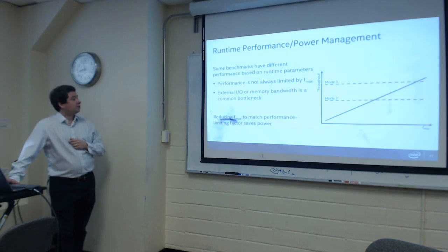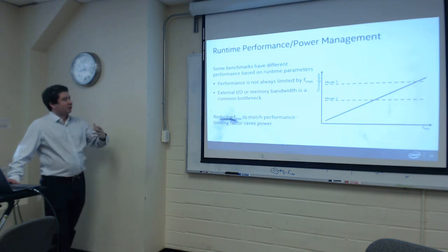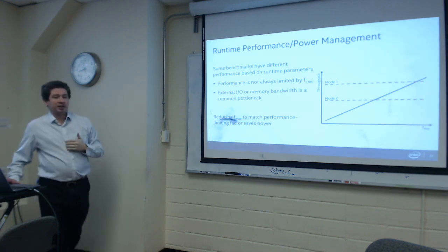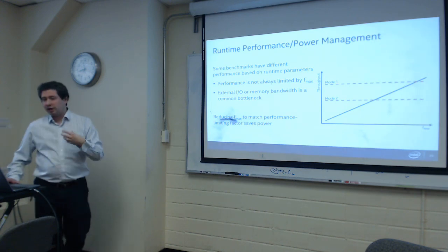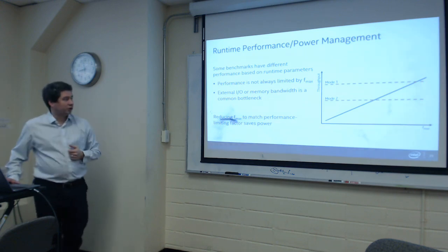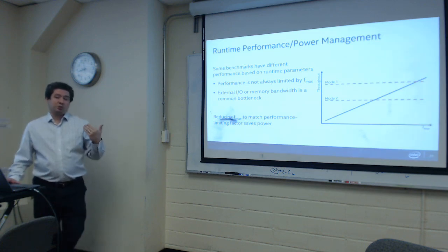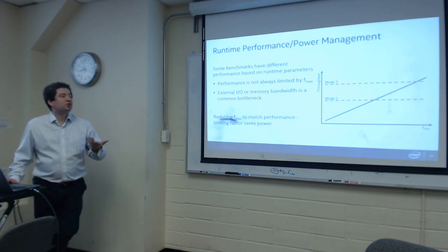Now, the last part I wanted to talk about is this idea of runtime management. Devon's work is a seminal work in that category for FPGAs. I'll talk a little bit about different strategies. In some cases, you may have applications that are not necessarily limited by clock frequency. What does that mean? In a system, you usually don't just have an FPGA. You will have some sources of data, some communication interfaces that allow you to exchange data with the outside world. If the I/O interfaces or, say, memory bandwidth is limiting your performance, then you could possibly be running your design at a much faster rate than it is useful to process that data.